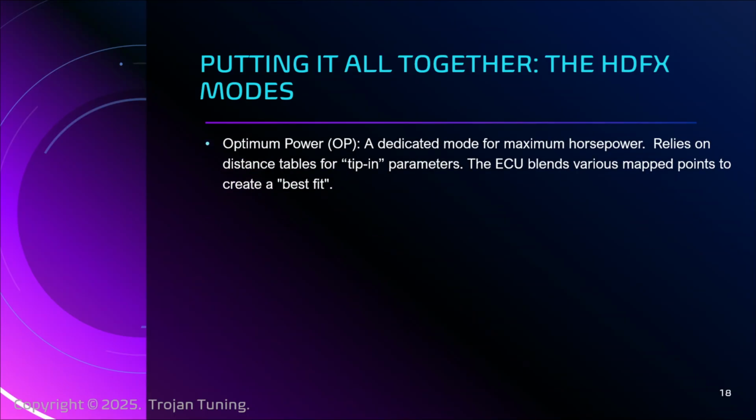Optimum power. This is the fun one, okay? When you are at wide open throttle, the HDFX looks at the distance tables and says, okay, here we go. It moves to the map point that is quicker to get to a point where you've got maximum breathing, maximum fueling, maximum power, right? Tipping in to get there is something that the HDFX manages for you, so it seems smooth, both going into wide open throttle and coming off wide open throttle. It's the bread and butter, right? It's the reason we do all of this, that mode.